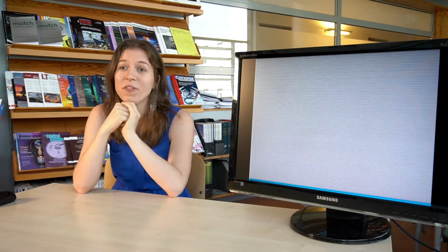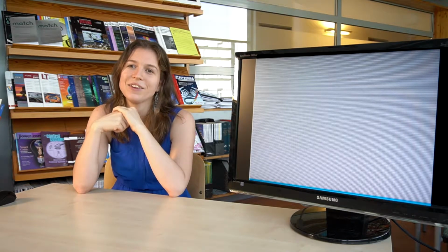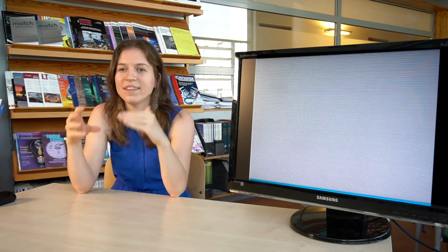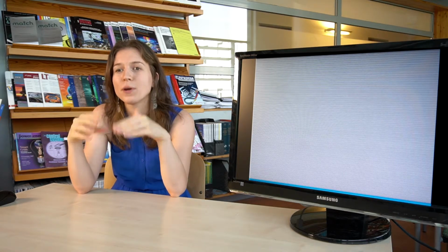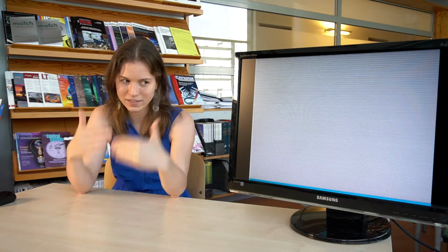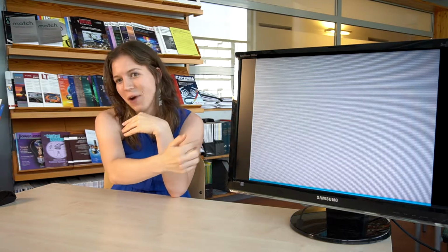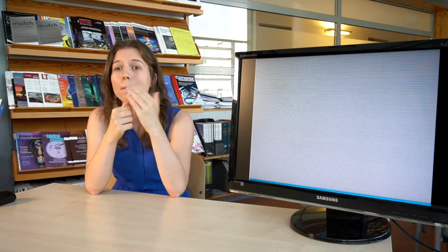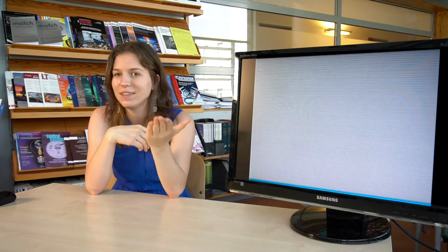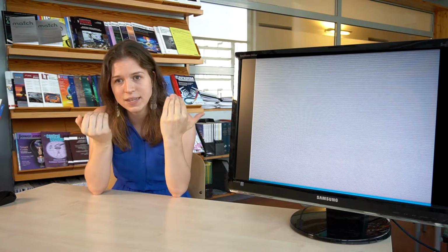And this is where the Nyquist theorem will come into picture, which says that your sampling frequency should be at least twice as high as the highest frequency component of your signal. So in this case, in this image, the highest frequency component is the striping of the screen, but the detector may not be fine enough to get this striping, to get this detail.